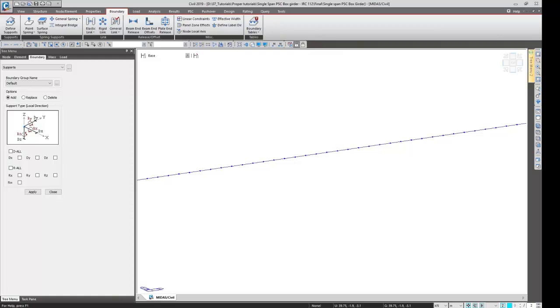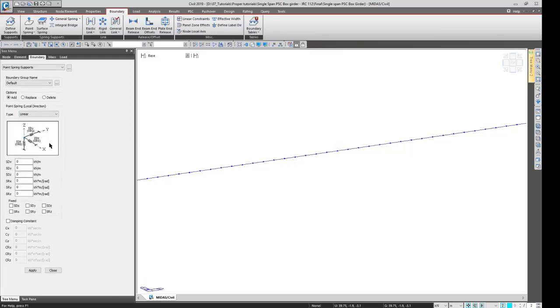Any questions on this? So let me just tell you how the soil springs are. It is nothing but a simple spring support, right? You can tell what the stiffness value is, and based on that stiffness value, force transfer would occur. Now, this is for the general case. Under soil springs, we have different types: compression only, tension only, multilinear. Now, we know soil doesn't resist if there are tensile forces.